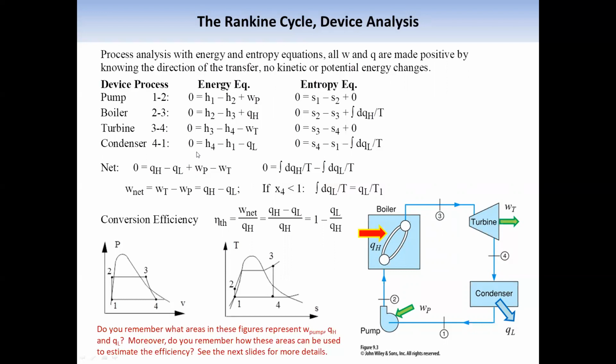So we use the energy balance equation we learned back in chapter 4, simplified. We can eliminate the kinetic energy term. We can eliminate the potential energy term for the total enthalpy. We can assume the process operates in adiabatic condition, so there's no Q term here. For the boiler, we don't have a work term. Instead, we have a Q term.